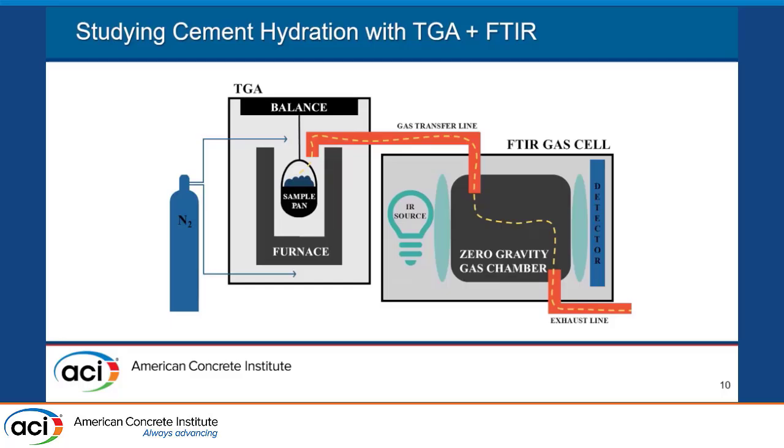Another area of research that we work on is understanding the degree of hydration. How much of our cement has been converted to hydration products. It's a whole different world once you start adding new additives. A lot of things can change, and a lot of our old techniques don't quite give us the right picture. So normally we would take a hydrated cement paste, thermally decompose it, and measure the mass loss and correlate that to how much hydration products have been developed. Then we compare that to a late age sample and we say, okay, great, this is 75% hydrated. We can go forward predicting strength.